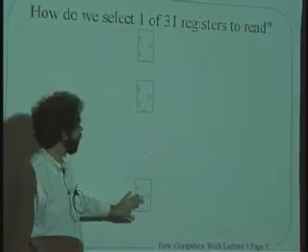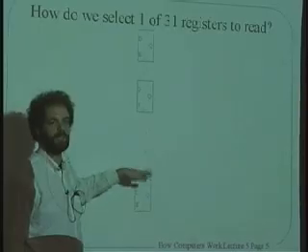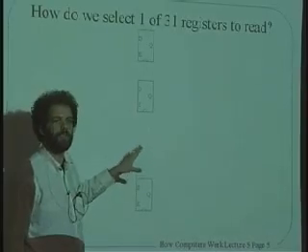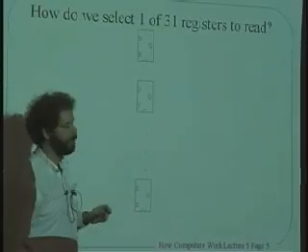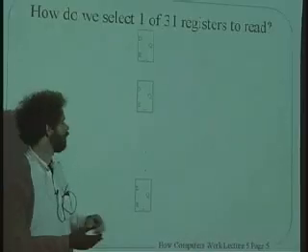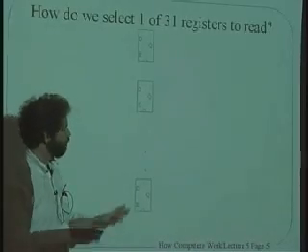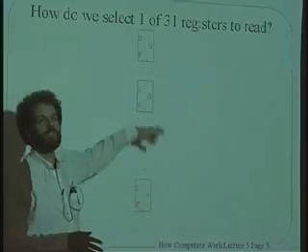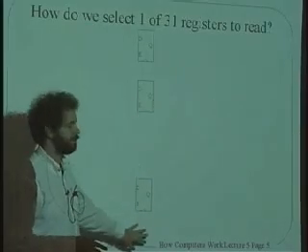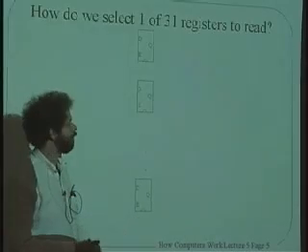And if you remember, R30 and R29 and R28 were special ones that we're going to use for special purposes, like the stack pointer and the linkage pointer, the base frame pointer and the exception pointer. That doesn't matter. We still have 31 registers. And then this last funny one, which is all 0 all the time.